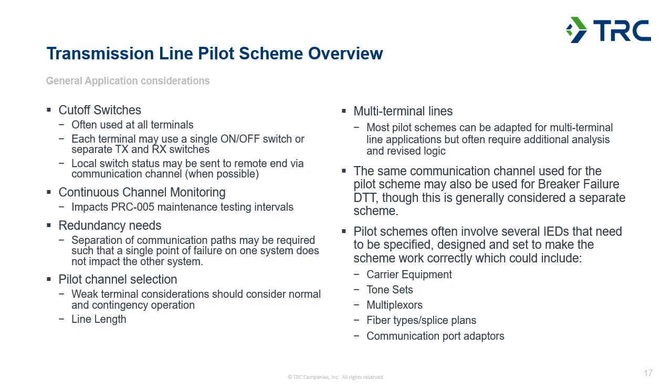So you have to understand both the fibers themselves and how they're spliced and make sure you're getting the right pairs of fibers between the two stations. And you may have some port adapters and things like that that also have to go into there. So, past just the basic protection requirements of these schemes, there's a lot that goes into the communication side of it that we as protection engineers have to understand in order to be able to make sure the schemes can operate reliably for all possible scenarios.